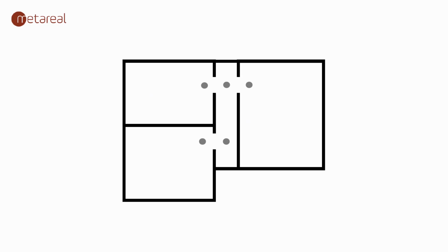Now, when shooting a tour, one thing that's very important to do is shoot panoramas both sides of any entrance and exit to any room, for example here and here. This will ensure that when the user's moving around, they can get through the door properly without sliding through walls or being unable to basically stand in a doorway.